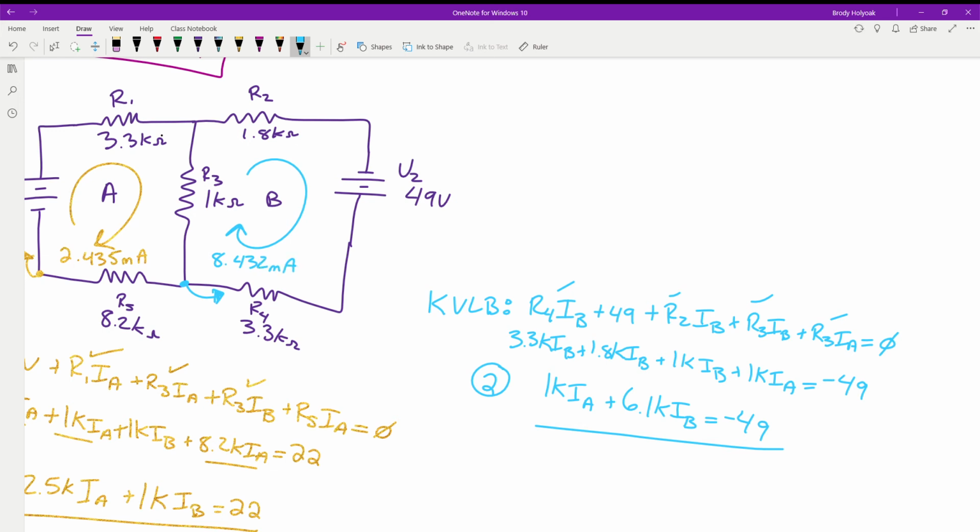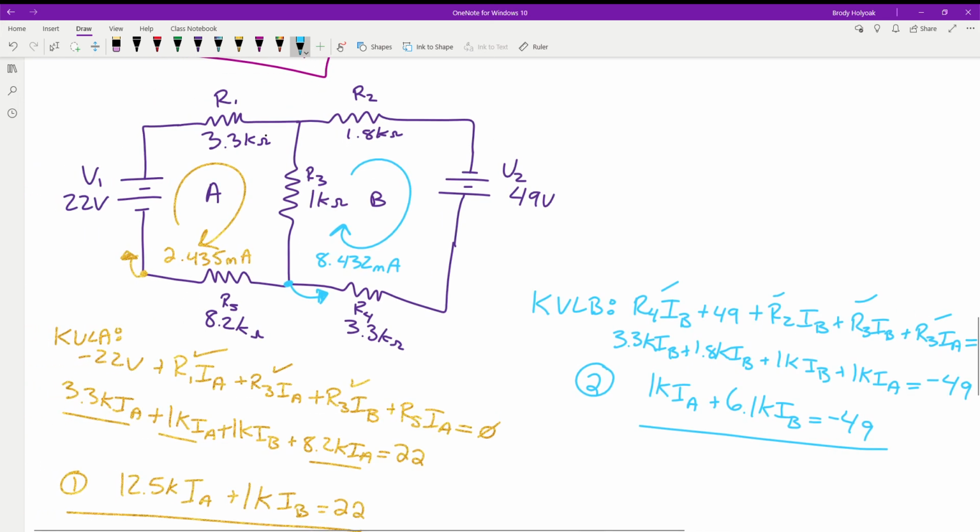So how is that going to work since the current total has to go to R1? Or no, because there's two power sources. This one we won't be measuring current total because there's no one place that we can measure total current. Essentially, from R3, that is going to give us the net current of these two voltage sources working. And that's where the focus of the answers is going to be, across R3. So what current do we have flowing across R1? 2.435. How much do we have flowing across R5? 2.43 milliamps. And that's going to give us polarities in this direction.